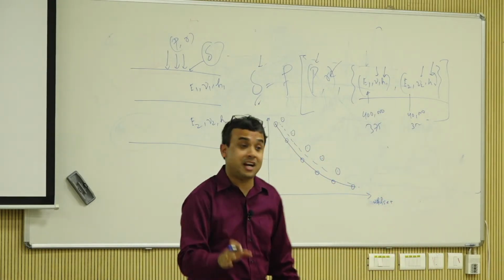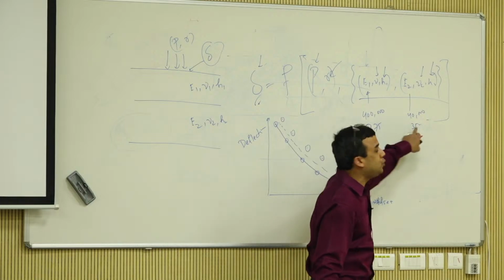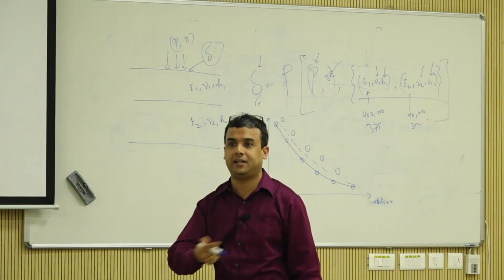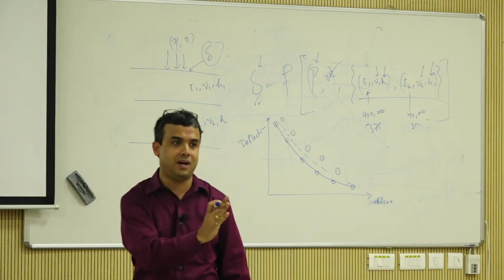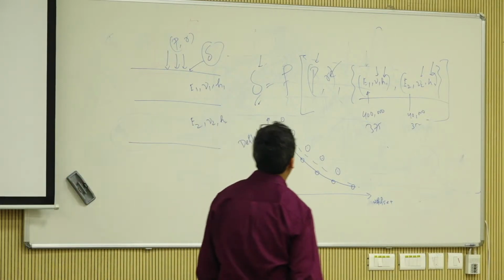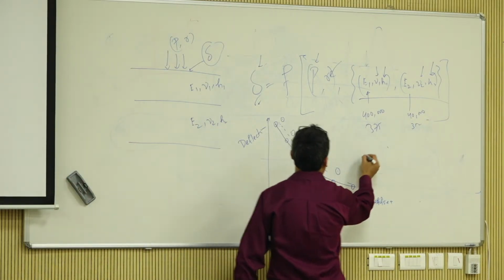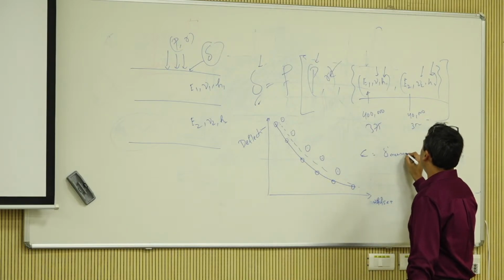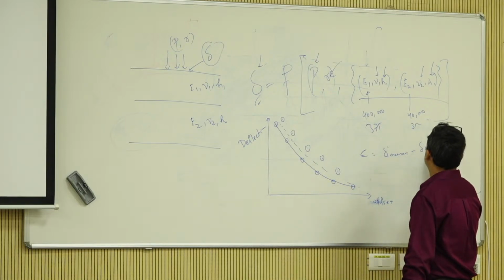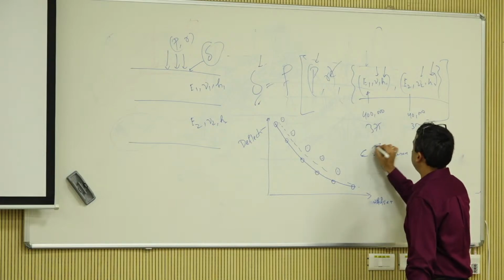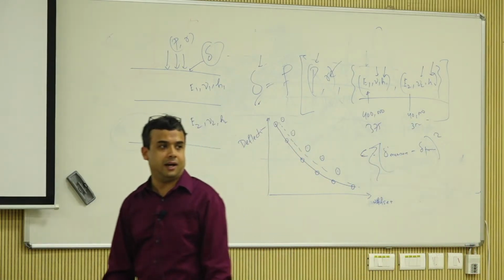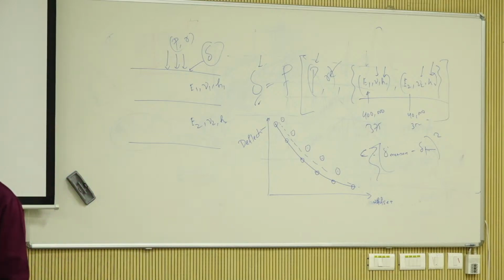It's not that straightforward, because if you change the two values together, you're going to be chasing your tail your entire life. You have to have a strategic approach, and there are convergence algorithms where error is equal to delta measured minus delta predicted, squared, summed for all the sensors, and you just do that, right? So that's back calculation. There are many softwares available.